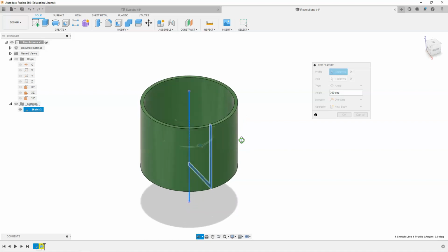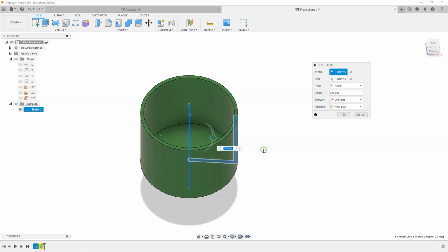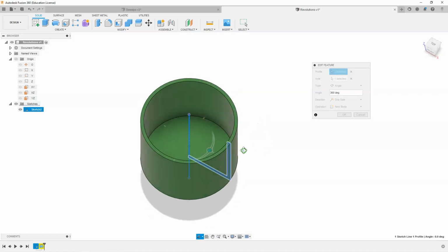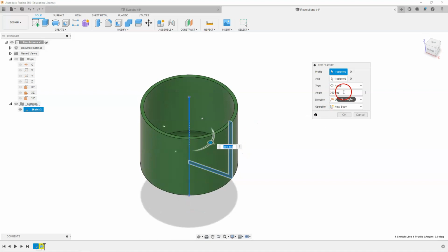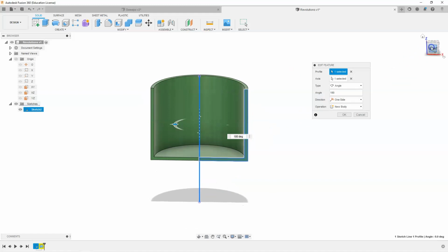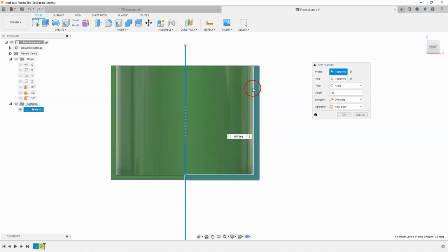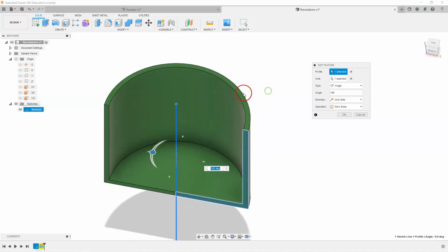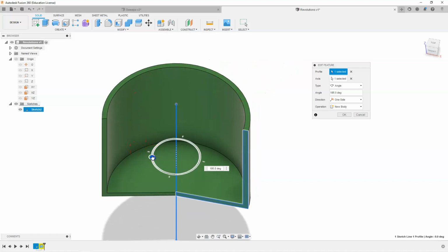So back to our previous work when we've actually created the cup using a couple different methods, using extrusion, using the shell. We also could have made this using a revolution. Just to demonstrate this, I'll change this to 180 degrees so you can see our profile. Look at our sketch profile there. That is the reverse L, and it is rotating around that axis 360 degrees.